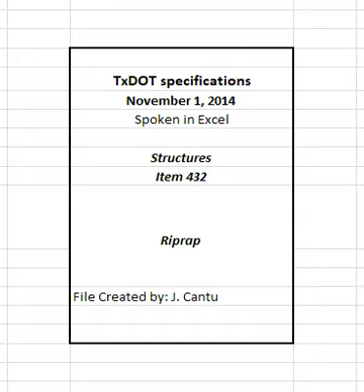3.2.2.2 Grouting. Construct riprap as shown in Figure 3 on the stone riprap standard. Size, shape, and lay large flat surface stones to produce an even surface with minimal voids. Place stones with the flat surface facing upward parallel to the slope. Place the largest stones near the base of the slope. Fill spaces between the larger stones with stones of suitable size, leaving the surface smooth, tight, and conforming to the contour required. Place the stones to create a plane surface with a variation no more than 6 inches in 10 feet from true plane. Provide the same degree of accuracy for warped and curved surfaces.